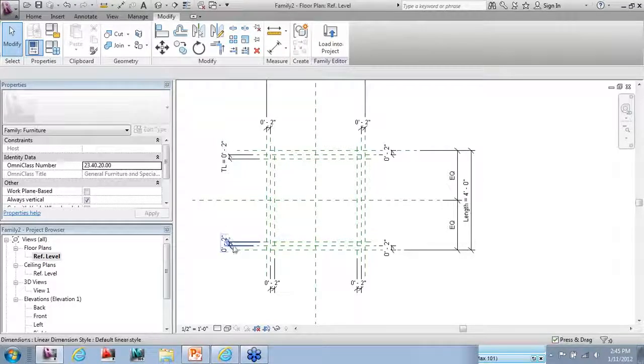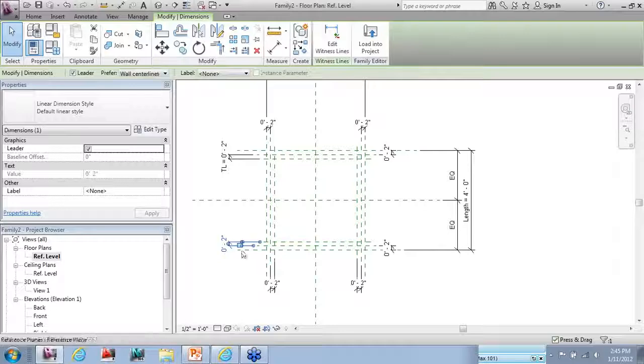Now what's great is I don't have to do that same process over and over again. I don't have to select the parameter, go in, add a parameter. What I can do, because these parameters are all the same, is simply select them, go to the label, and apply a label. So another nifty trick is the ability to apply a label to a said parameter.